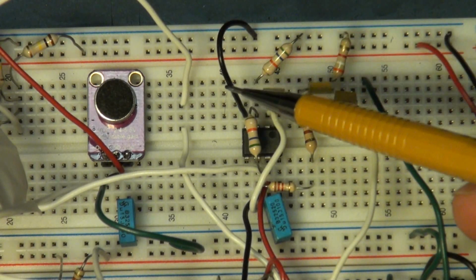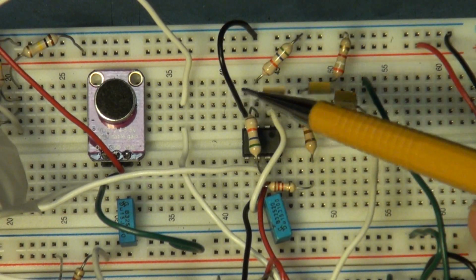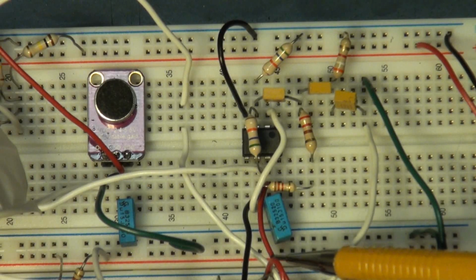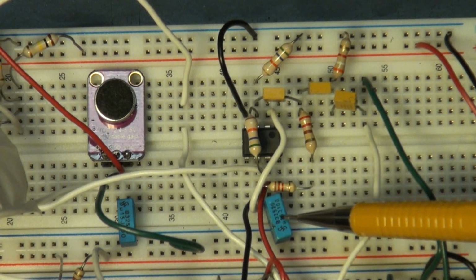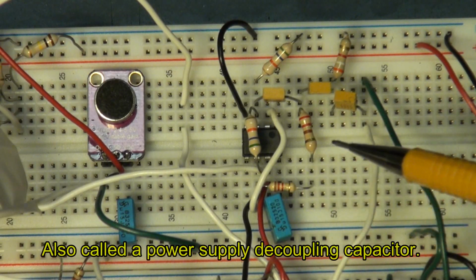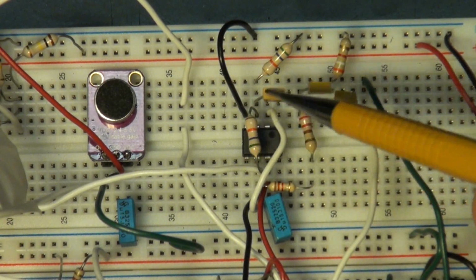So pin 4 of the op-amp is the ground wire. Pin 7 is the V plus, positive 12 volts, and this little capacitor here is the power supply bypassing capacitor. So R3A, R3B resistors are right here.